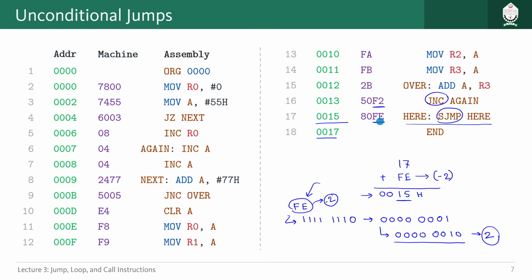But you have to understand, because we have maximum of 8 bits for representing relative address, that's why in forward direction we can go 127 locations at maximum of ROM, and in backward it should be 128 locations, or 128 bytes you can say, because each of the locations can have 8 bits of storage. Okay,